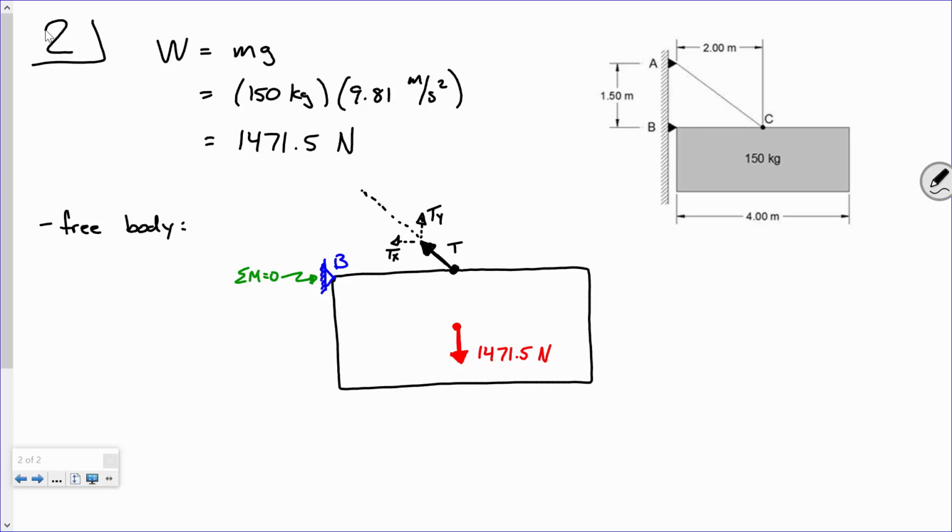Let's say you and I are holding a rope, okay? And we're pulling 20 pounds, right? So you're pulling 20 pounds and I'm pulling 20 pounds, right? We're sitting still, tug of war, right? Neglecting how much the rope sags, does it really matter if you and I are here or if I'm all the way over here? We're still pulling 20 pounds. So where I locate this force can go all the way up and down that line. I can say that Tx and Ty is here. I can say Tx and Ty is here. I can do anything I want, okay? What I'm going to do is put that Tx and Ty right there.